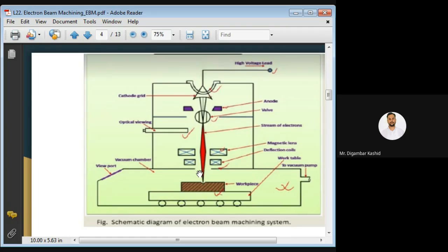Okay, from the chemical backing material, high velocity gases are generated. So this gas, when it is coming outside with a very high velocity, expels whatever molten metal is there. Molten metal means vaporized material, the material that has been removed.